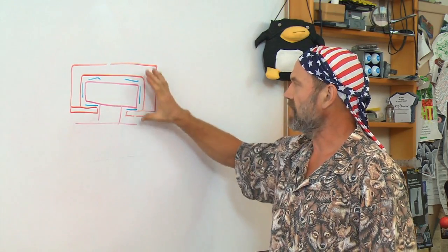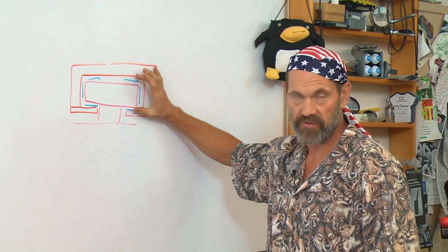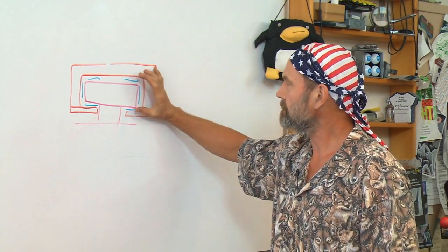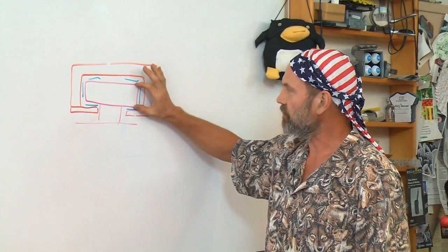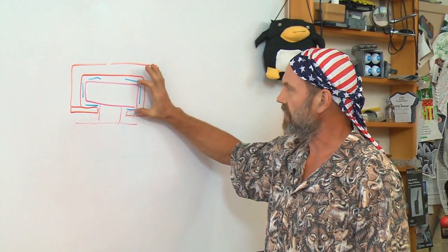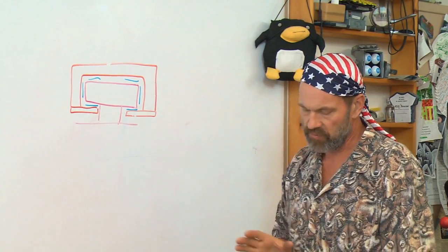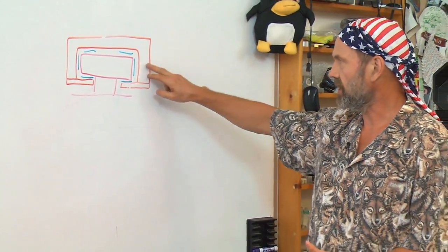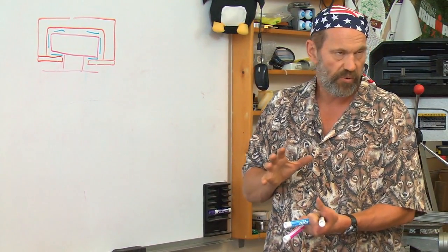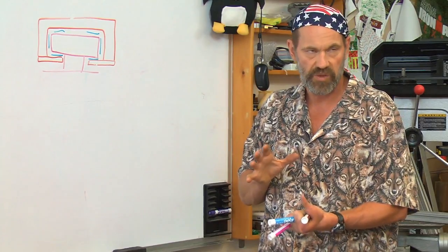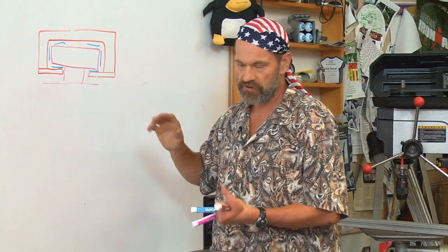These act as springs to keep this whole thing preloaded together, as we'll talk in a minute about the importance of preload in bearings. It also allows for locally, if the rail has a variation in height, if this keeper plate was really stiff, as I move the carriage, this is called the carriage, this is the bearing rail, along, I'd come to a point where the bearing is too stiff and will not allow local deformations to occur.